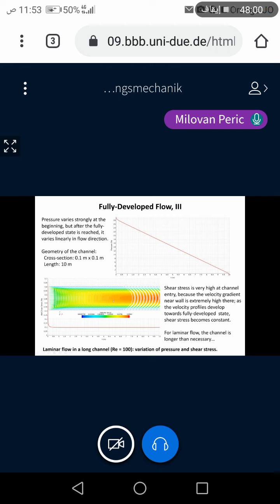And that's why I showed here also again the velocity vectors. This high shear rate at the inlet is due to specifying constant velocity. So if you have a grid here, which I didn't show, every velocity vector is basically in the center of one cell. So you see how many grid points are there.